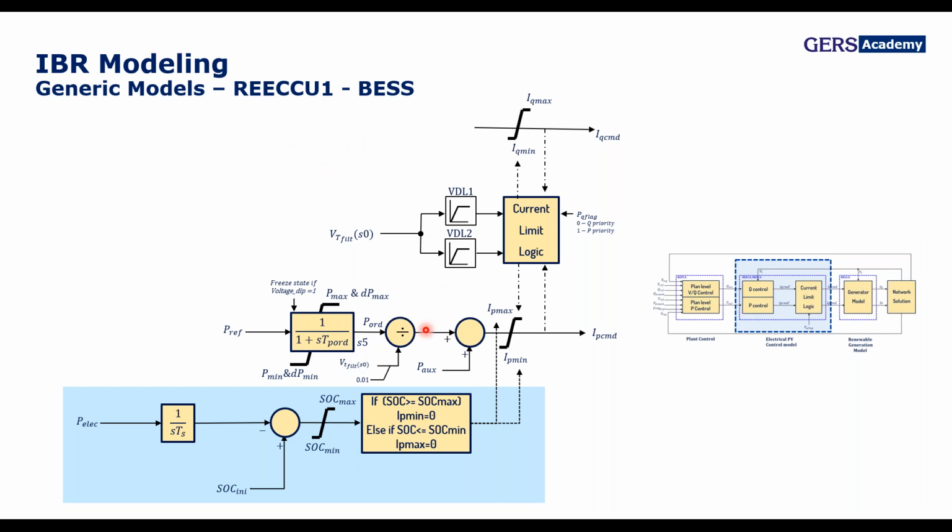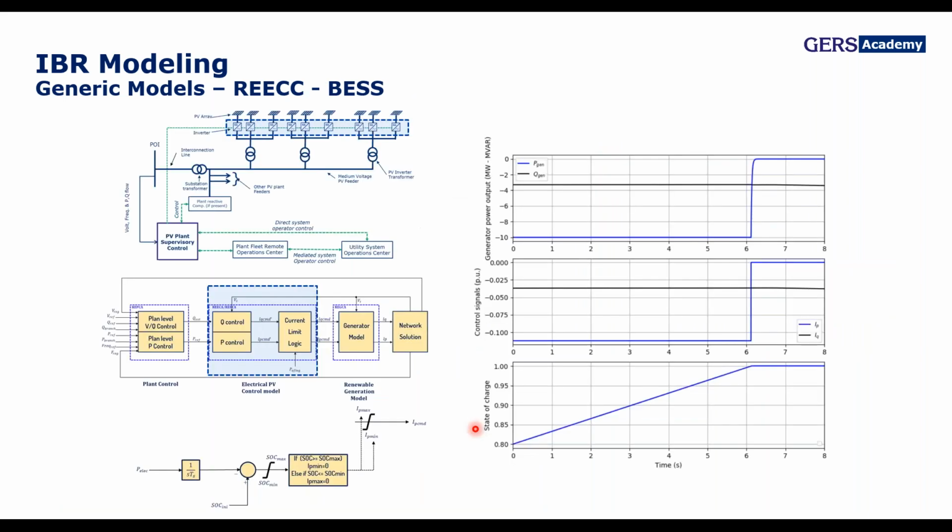And finally, if you are including battery energy storage, most of the latest projects include some kind of active power reserve. You will have an extra control loop that tries to ensure that the battery is charged and can be discharged into the system, or the opposite, that the battery is discharged and needs to charge from the system.